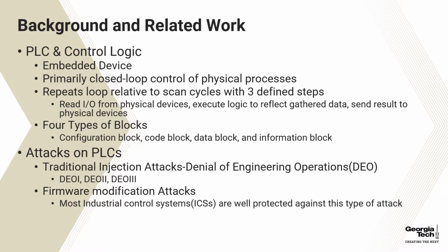As a little recap, PLCs are embedded devices, primarily closed-loop controllers of physical processes in real time. This loop is repeated in 3 defined steps. These steps are reading I/O from physical devices, executing logic to reflect the gathered data, and sending results to the physical devices. Next, you have 4 types of blocks.